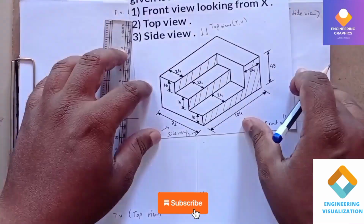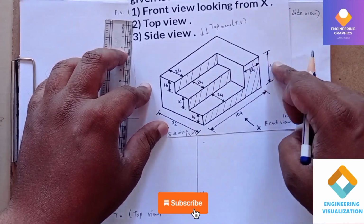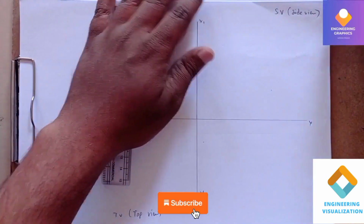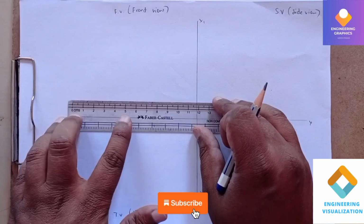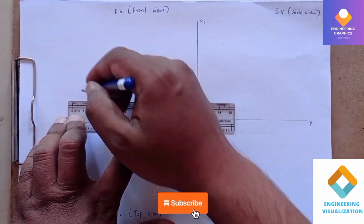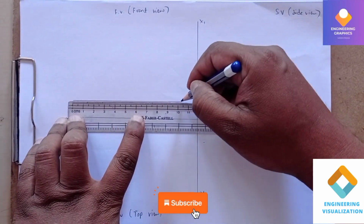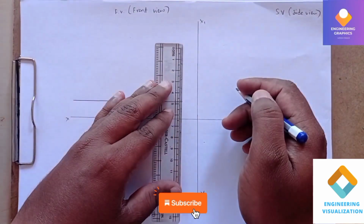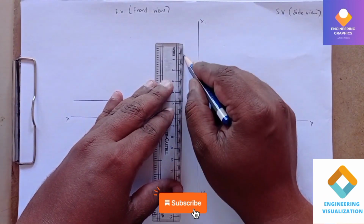We need to draw it. You can see the length is 104 mm, and the height is 48 mm. That means we can construct one rectangle of 104 by 48 mm with thin lines. So I'll be drawing a horizontal line here for 104 mm. You can see all these dimensions are in mm. So 104 mm. The height here we should get is 48 mm. So mention 48.